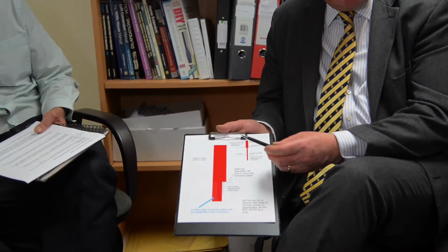Now, normally in the lower storeys, if you look at this little sketch here, you can see what happens when you're taking away a section of the chimney breast. You're left with the core wall, which is fine on the other side. You've probably got enough stability. You put in a gallows bracket here so that you don't lose any material above.